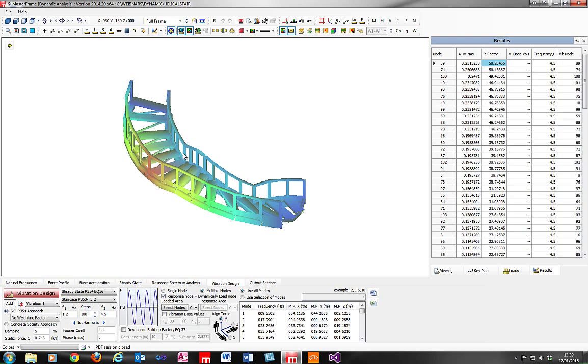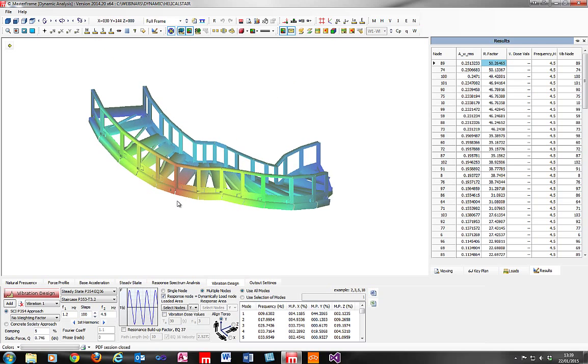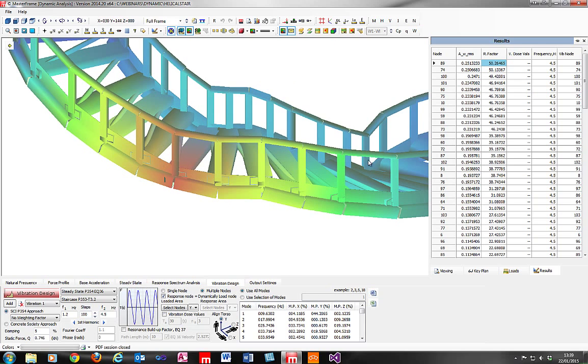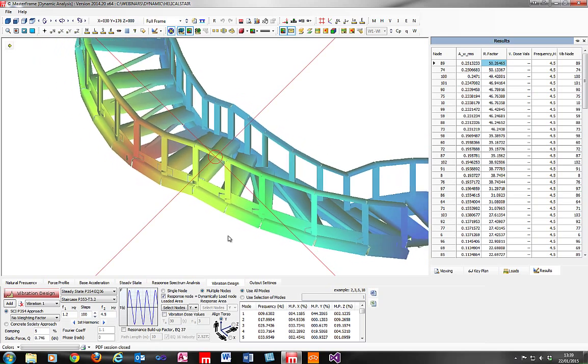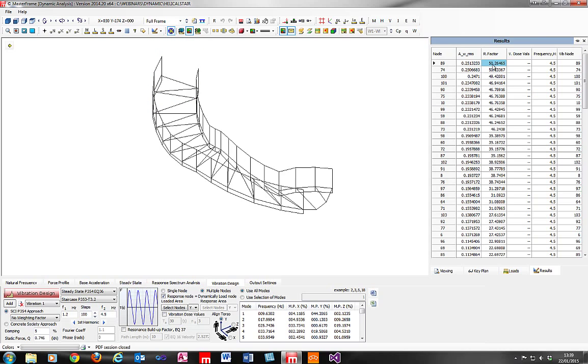We saw the color-coded ranging that you got for the finite element shell elements, but when you turn on the 3D button, when you've considered response factors for a multiple range of nodes, it will color code them, giving you a little red hotspot to allow you to zone in on the parts of the structure that are important. This is always ordered from highest to lowest anyway, and when you select that you usually get the red dot appearing as well, so it's generally not that hard to identify where you are in the structure and what is important.